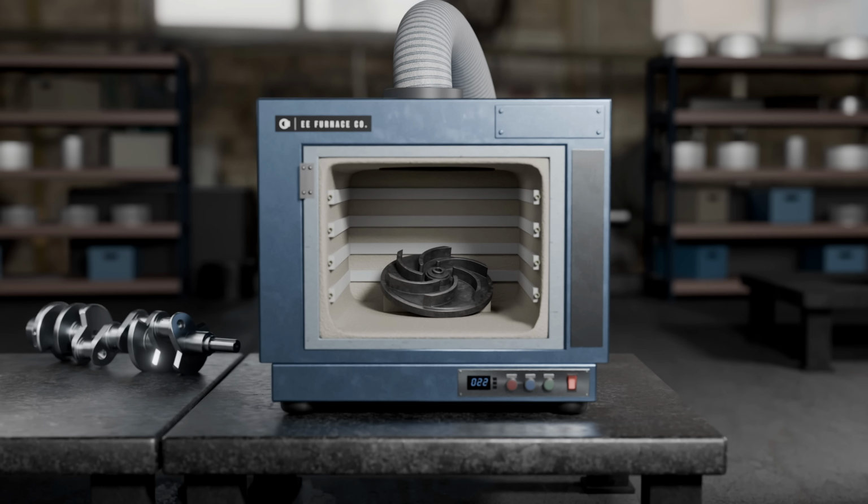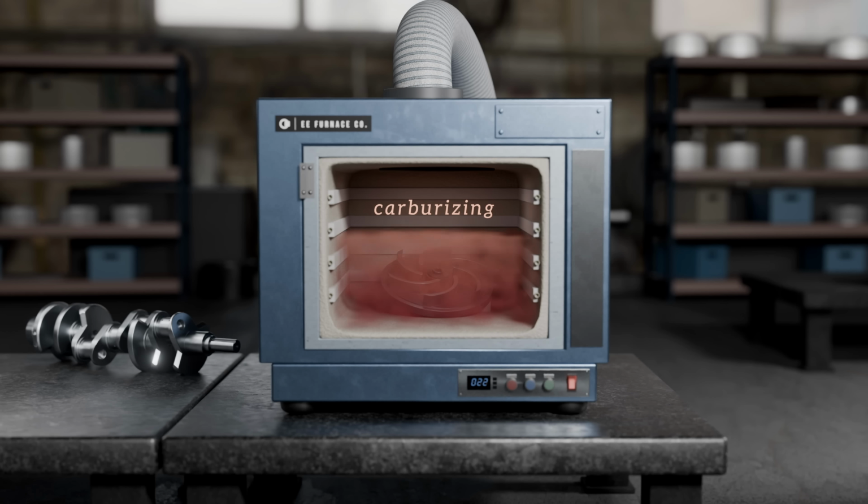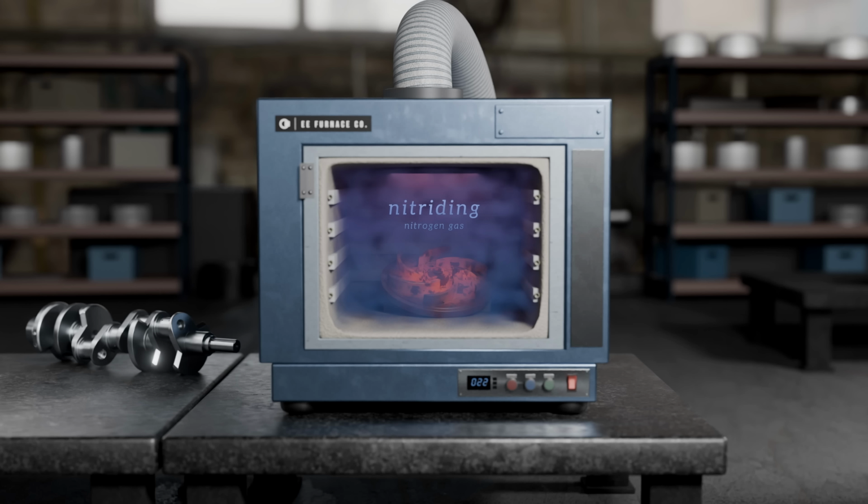Carburizing involves heating the part in a carbon-rich environment to increase surface carbon content, followed by quenching. Nitriding introduces nitrogen into the surface to form hard nitride compounds, without the need for quenching. A big advantage for precision parts, since it avoids any warping that can occur with quenching.